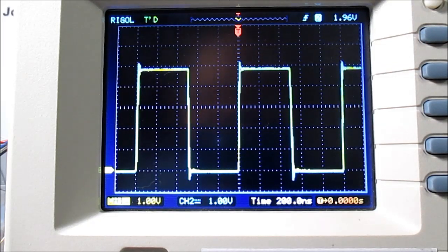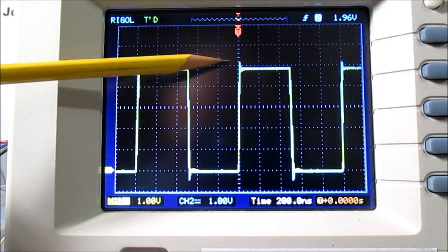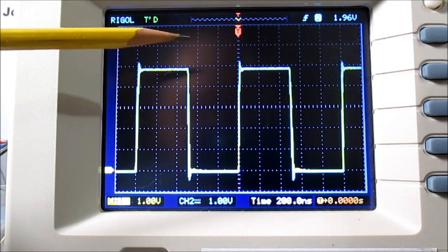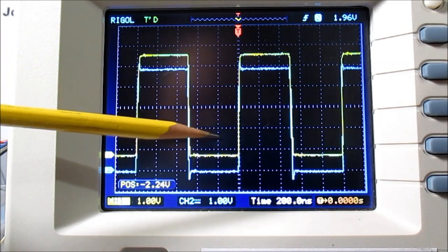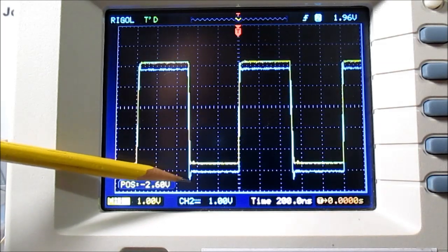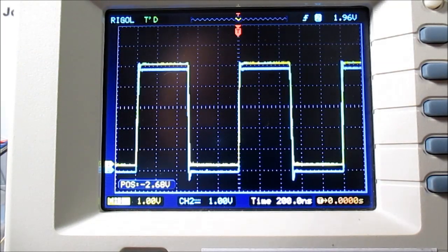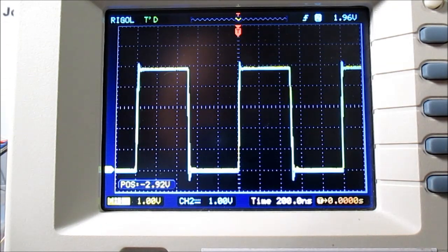Those microcontrollers can give you a nice waveform. It does have a little bit of overshoot. See, I have the channels on top of one another, but the direct output of the microcontroller does have a little bit of overshoot. That's not my scope probe. It is actually that way because when I move the lead to the same place, I don't get that anymore.